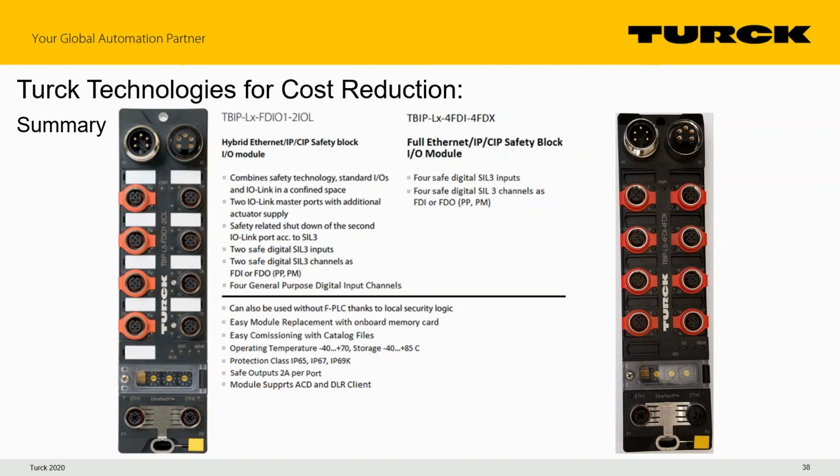And that hybrid becomes useful if you do your safety calculation and find out that the network update times are adding too much time to your safety mode, where the time between input action and actual stoppage. You can now have local action take place faster in the block, but still pass that information to the safety PLC so that it safely shuts down everything around it. So we do have that mixture of modes available.